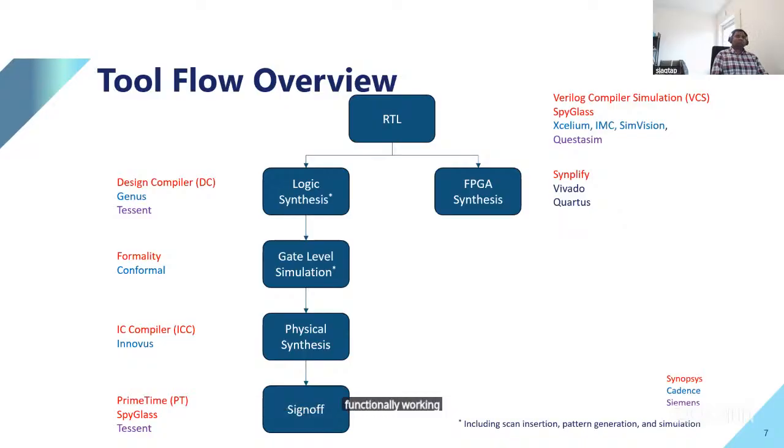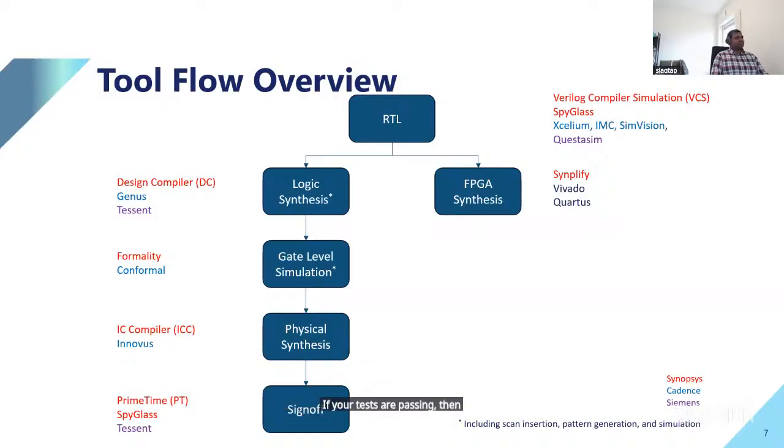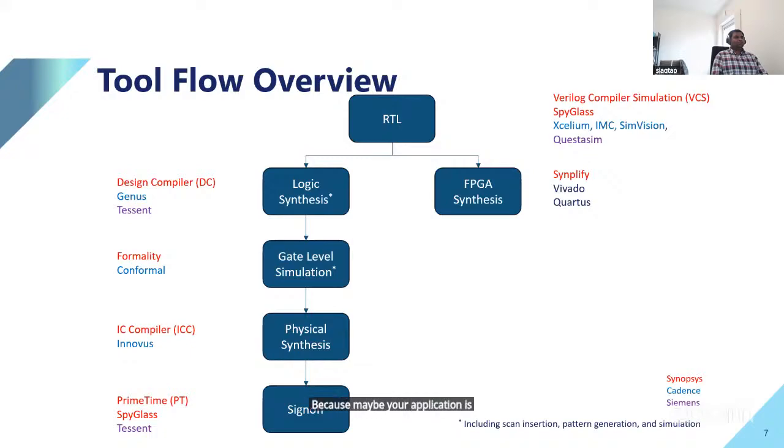Of course, one way of testing the chip is to run those test cases again on the chip, and if your tests are passing, then the chip is passing. But that cannot give you a 100% guarantee that everything is really working, because maybe your application is not simulating all types of scenarios you will face in real life. So for that, there is a structure called scan insertion. I will show in quite some detail what scan insertion is and what the tests look like.